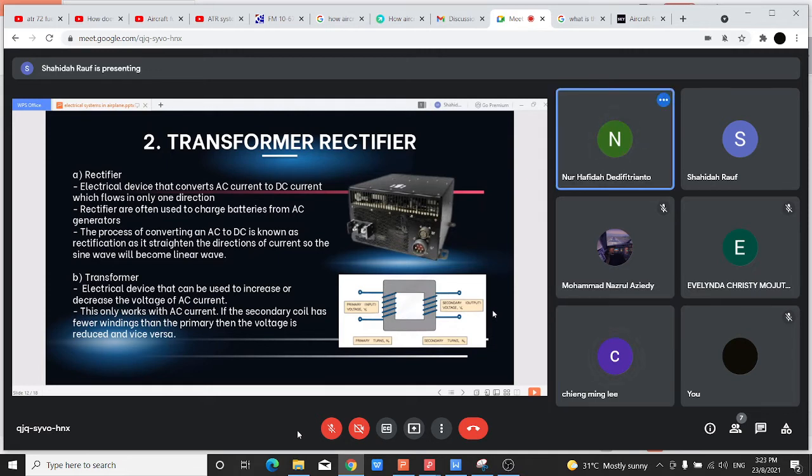For an aircraft, it's normally on. Once your APU is running and the engine is started, and the electric generator from your engine gives enough power, you will trip the APU supply. This means only your engine will supply the DC power and AC power.